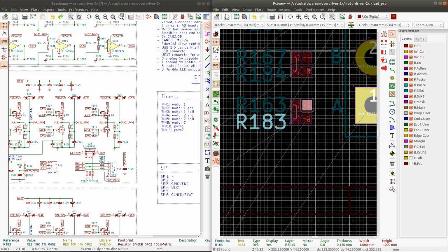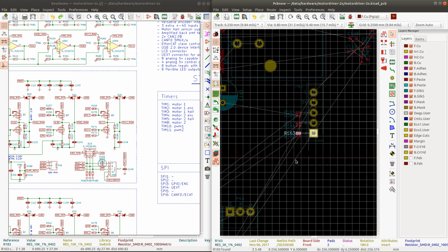An annoying thing with KiCad is that it doesn't yet have the functionality to allow you to place components so that they don't intersect. At least I don't know if it has that. I haven't seen that yet. That's very useful functionality that Altium has, that you can just have the components aligned by the courtyard, but in KiCad you have to actually place them on the grid.